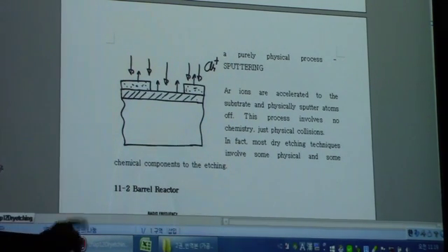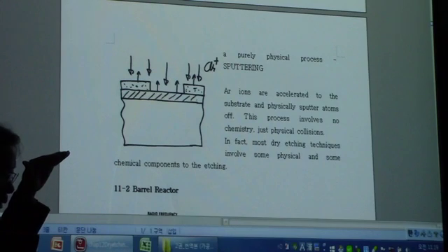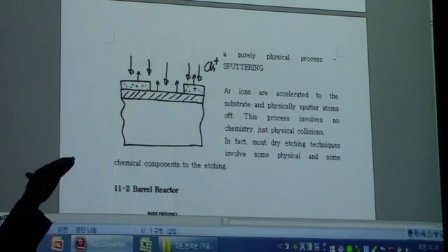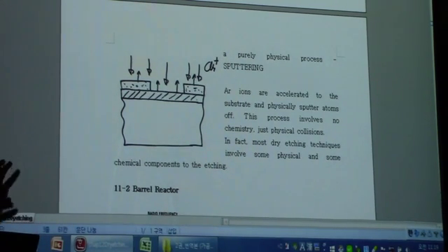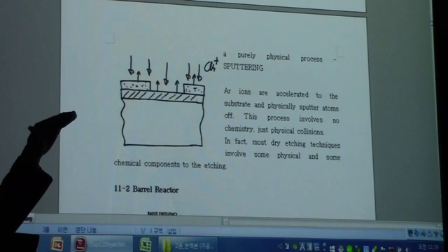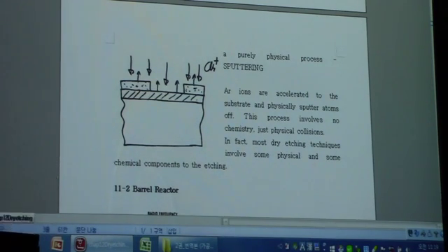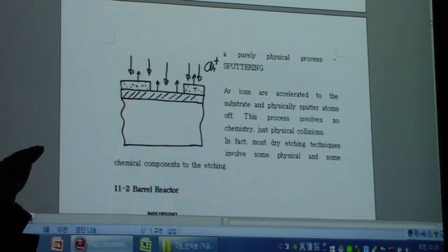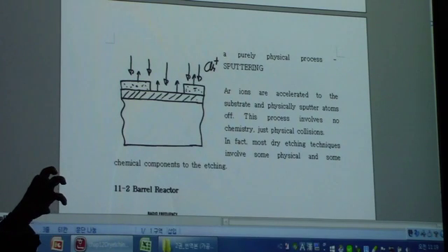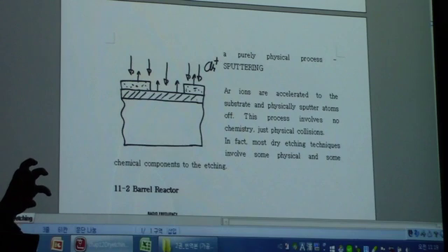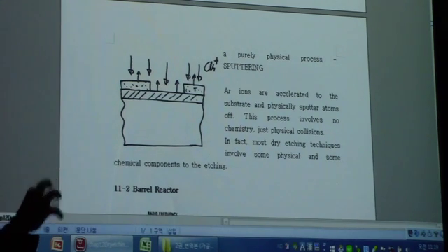When you apply the RF between the two electrodes, the ions are moving very slowly compared to the electrons. So even if you apply the AC between the two electrodes, you can find a DC characteristic inside it, because the ions, which are positively charged, and the electrons, which are negatively charged, are moving differently.